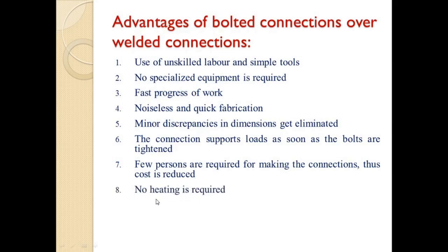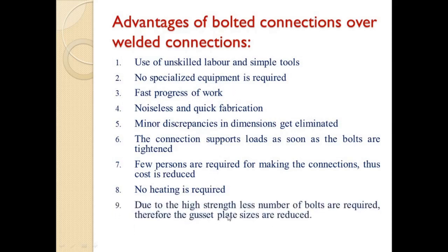Next, no heating or electricity is required for bolted connections. Next, due to the high strength, fewer bolts are required, therefore the gusset plate sizes are reduced. In case of welded connections the gusset plate sizes are more. And lastly, it is easy to dismantle and reuse the material. We know bolted connections can be easily dismantled, and wherever we require, we can use these members.